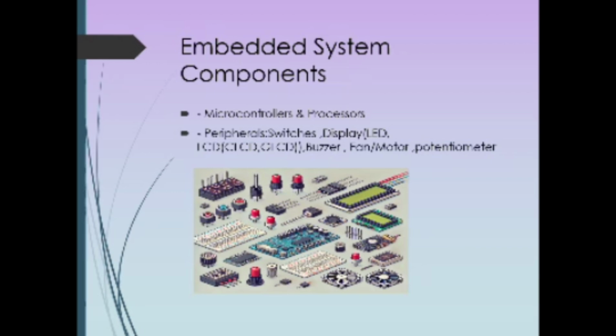Now we will come to display. In display, there are LEDs, which are light emitting diodes. They are used for signaling or as signals. Now going on to LCD. LCD first pin is the ground pin. Second is VCC, which means where we are giving the voltage supply. Third pin is the contrast pin, or we can say output voltage, or VEE.